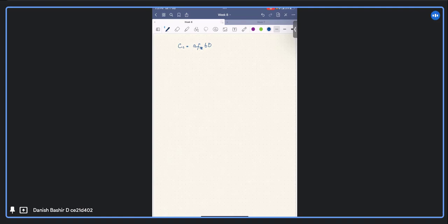So depending upon that, our A also varies like this. A is equal to 0.362 XU divided by D, if XU is less than or equal to D, that is, the neutral axis lies within the column.